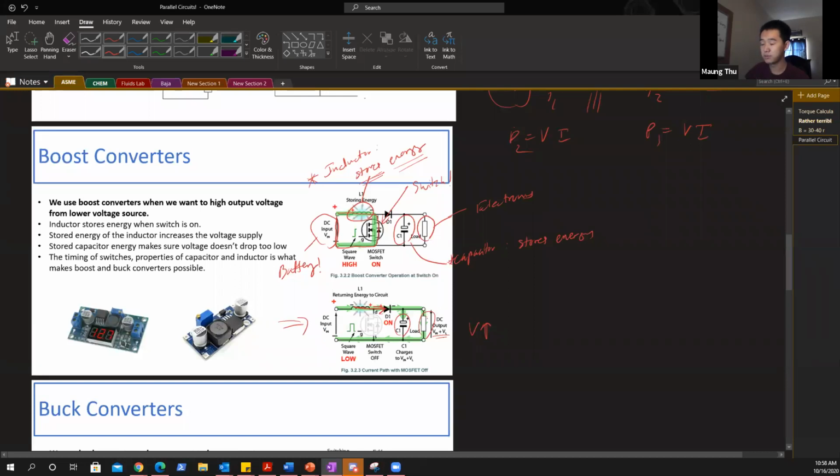So basically what the boost converter did is increase your voltage. When you have appliances that are, let's just say, 24 volts and your battery is only 18 volts, you can use a boost converter to get to 24 volts for those appliances. Most of the time, people don't use boost converters. They just pick a higher battery and then drop it down using buck converters. Anyway, once it is off, the energy gets provided, it completes this circuit, but afterwards it's going to turn back on again.